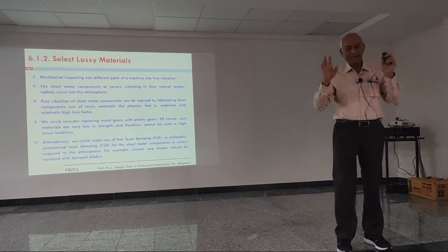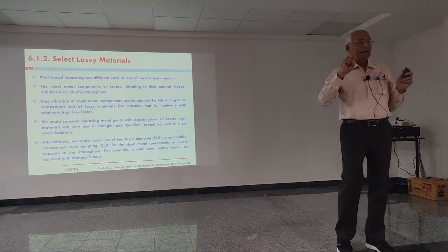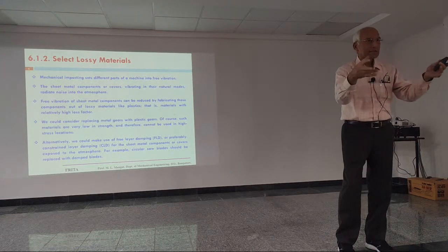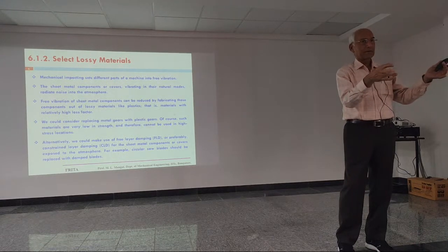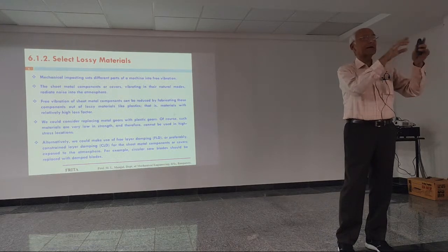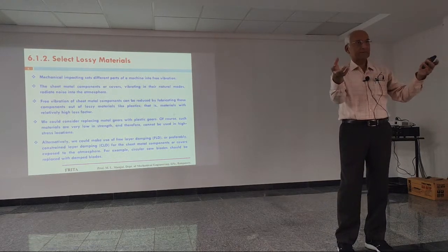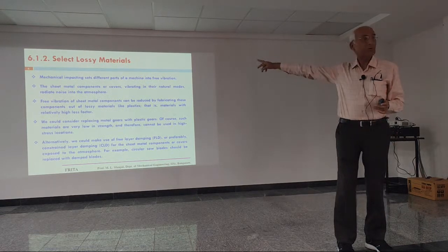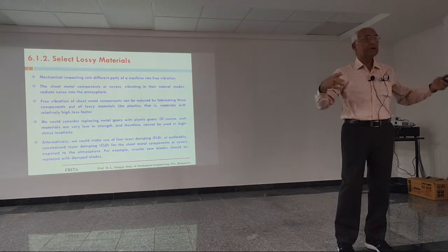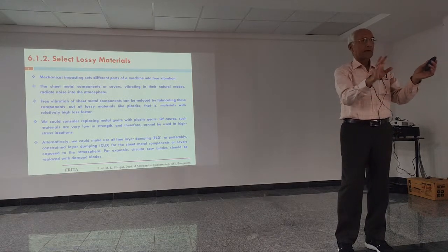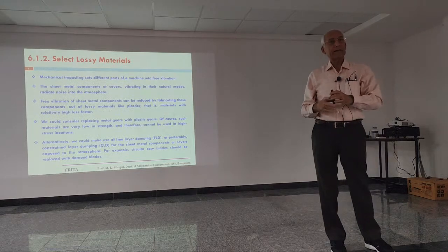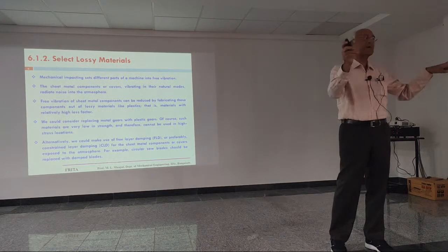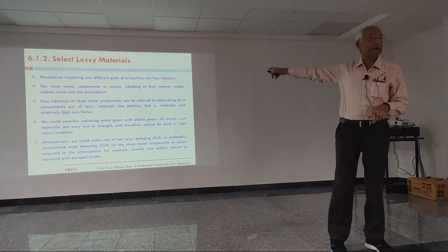I just said, listen, most of the noise is from resonance of parts. And resonance means free vibration of loose components. And I said all we do is we choose more lossy materials. We build in damping in the system. And the good thing about damping is that I don't even have to know the resonance frequency for which I am designing. All resonance frequencies will be damped if I have built in damping in the system.